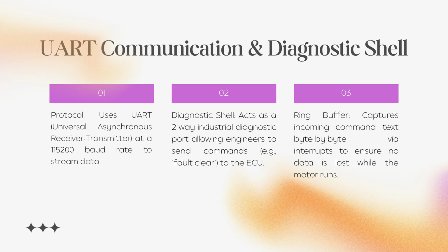To get this data out of the microcontroller, we use the UART communication protocol running at a speed of 115,200 bits per second. This acts as an industrial diagnostic port. Not only is the STM32 sending telemetry out, but it can also receive commands from an engineer.